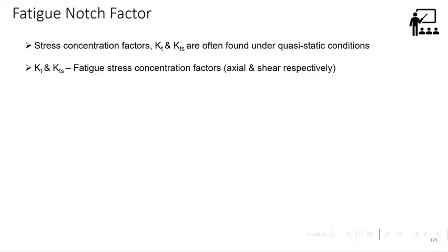It is not well known and popular, and not used, because we use the conservative factor K_t; the fatigue stress concentration factor is less than the theoretical stress concentration factor. So if you use the theoretical stress concentration factor and are able to meet your objective, whether life or anything else, then there is no point going into detail, spending time and effort to find out the fatigue stress concentration factor. That is well said and fair enough. But one has to be very careful about this.